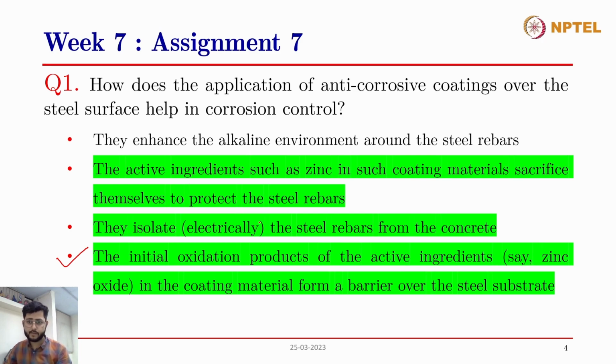Yes, they isolate the steel rebars from the concrete. So therefore, a decrease in the pH or the presence of chloride ions in the concrete won't affect the steel rebars as much as it will affect a system which doesn't have an anti-corrosive coating on the steel rebars, because the application of these anti-corrosive coatings isolates the electrochemical environment of the steel reinforcement from the concrete core that is present outside or far from the steel reinforcement.